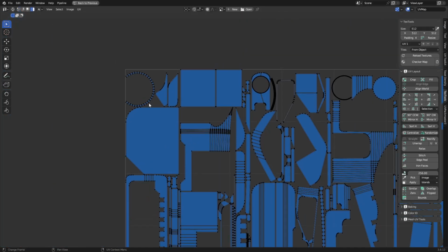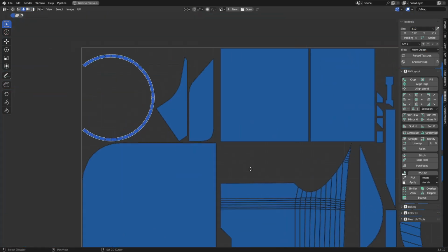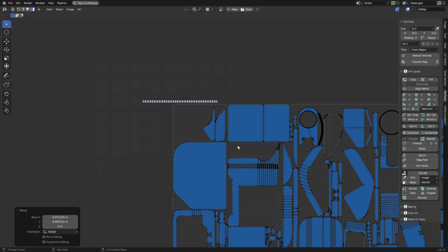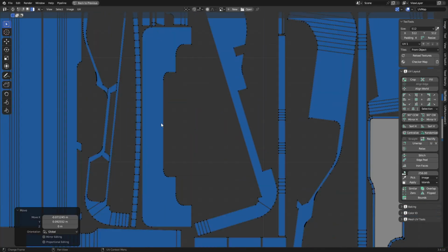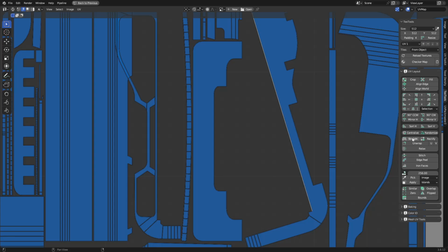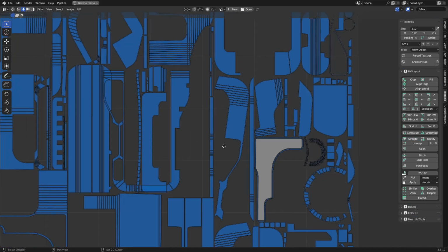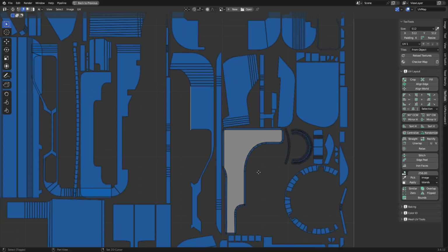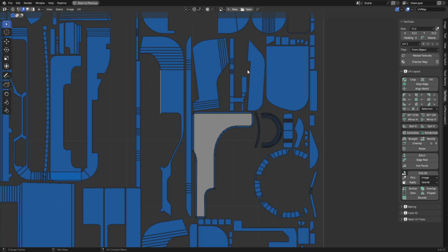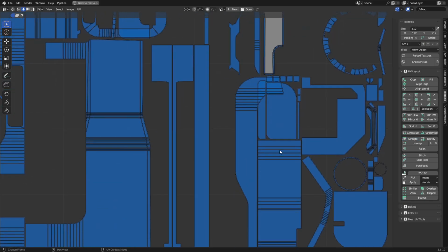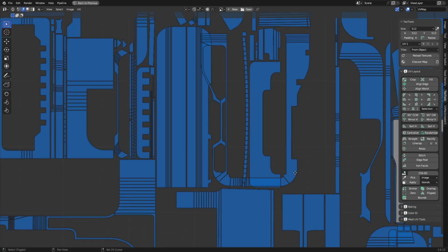And you get the TexTools add-on, for real. This is the best thing ever. Because when you have quad strips like this, you can just rectify them usually. Done. When you want to straighten something out, you can grab it and hit straighten, you see? It's freaking fantastic with those tools alone. With vanilla Blender's UV unwrapping tools, there are ways of doing stuff like this usually, but it's so far from user-friendly to do all these workarounds.